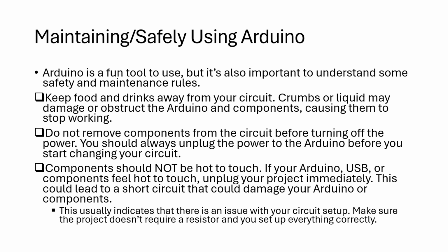Unplug your components if they feel too hot. When powering your project, none of your components, including the Arduino board and breadboard, should feel hot to touch. It should feel cold or slightly warm. If you're powering your circuit and notice something is rapidly heating up, immediately unplug your project and recheck your circuit. You may be missing a component or have set up the circuit incorrectly. Do not plug your Arduino in again until you've identified and fixed the issue. Failing to unplug the circuit could result in your Arduino smoking and eventually catching fire, so make sure to keep an eye out for any temperature issues.